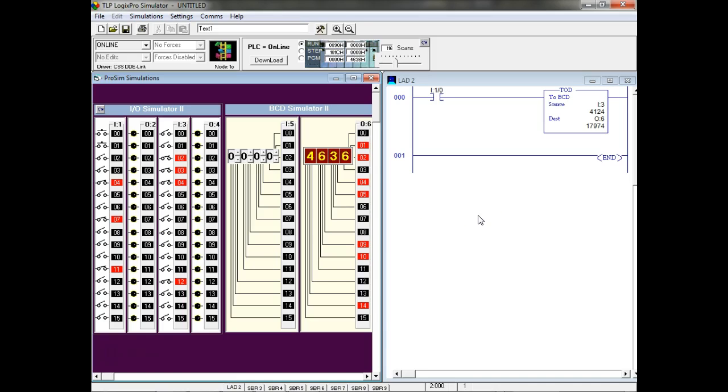Well, these switches right here, these are called thumb wheel switches, by the way. This is what a person would input, like a motor speed or a count I want a counter to be. But what base is this in? It goes from 0 to 9, guys. So what's it giving me? This is BCD. But if I sent this to a counter, it would interpret this as what? Starts with a B. It would interpret it as binary, right?